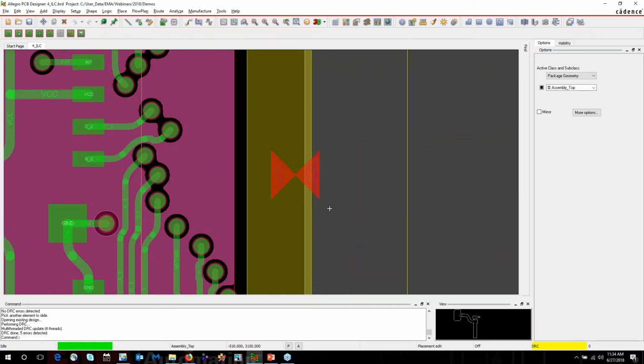And you'll see that I actually have a violation here, and it says IO inside my bow tie. If I float my cursor over it, you'll notice that it says it's an interlayer spacing rule, and we want an overlap of 25 mil according to the constraint value, but the actual value is only 10 mil. Okay, so to fix that, it's actually pretty easy.